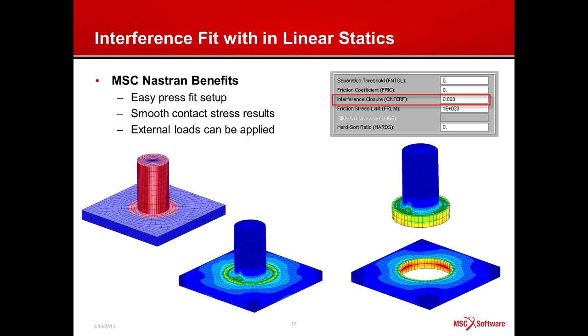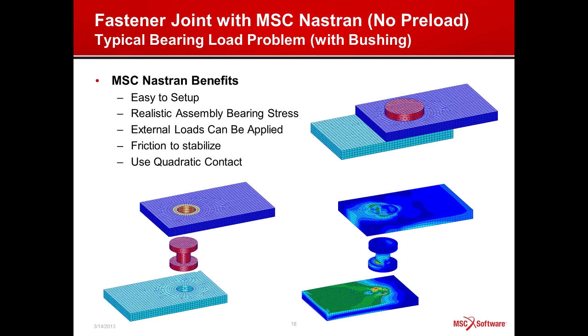Or if you already have interference fit in your mesh, you just leave it as is, and at step 0 of the nonlinear increment process behind the scenes, even though it's a linear solution, Nastran will recognize that there's initial penetration, move the nodes to the outlying surfaces, and induce the pre-stress due to the interference fit naturally. So that becomes very easy to do as well.